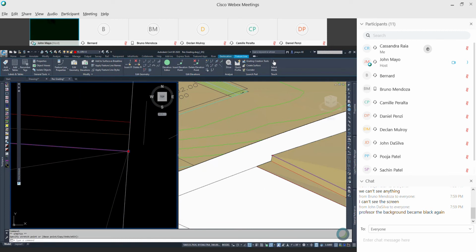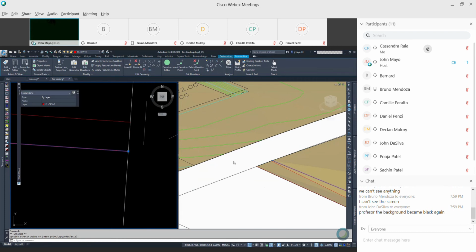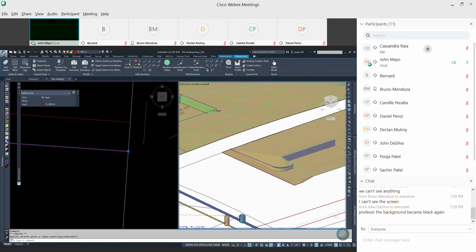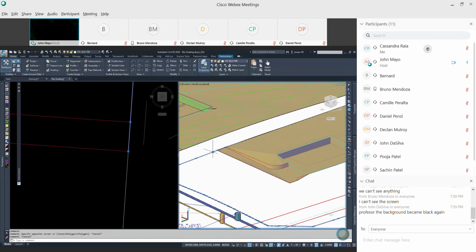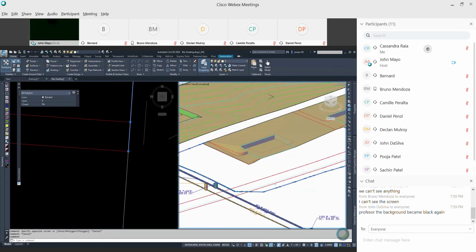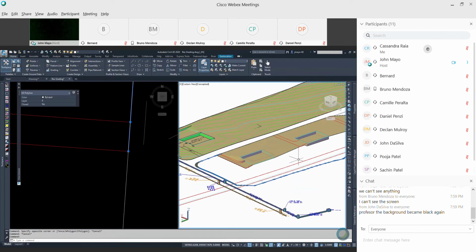And now we see my wall will taper down to 0 as well. One last thing to fix up, or 2 things to fix up. When I broke that 3D polyline, the border on my surface broke. And B, I lost all that surface definition.